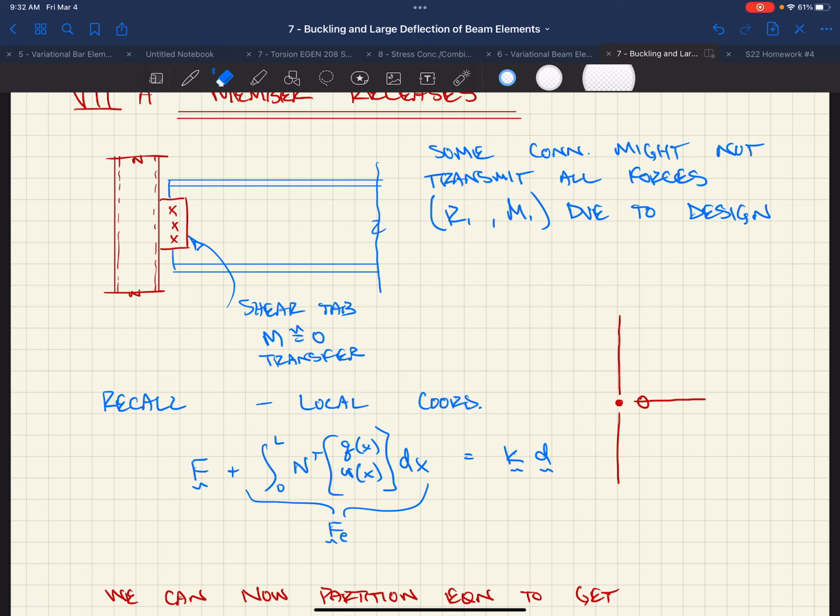But in that case, it was a round building. It was only supported laterally on half of the basement. You know, it's a clear story basement or open basement on the ground floor. And so you have this huge torsional behavior happening. So we had all sorts of redistribution happening from the top to the bottom of that building. And so you end up spending days being like, what the heck, scratching your head, thinking, what's going on?